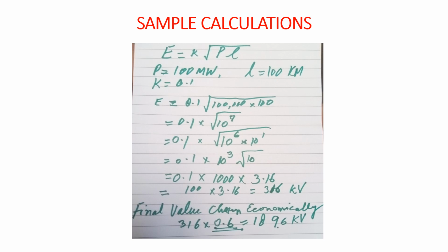Why? Because they are not looking at the problem in isolation. You are looking at your problem in isolation. This formula is in isolation. It is not taking care of the whole system, the whole network, the whole impedance, the power, the short circuit level, etc. So this formula does not take care of all those things. The utility company looks at the problem in the big picture, at the whole system, and the basis of the decision will ultimately be load flow studies, power system stability, steady state stability, transient stability, and short circuit studies. So all those things will ultimately control the voltage selection.